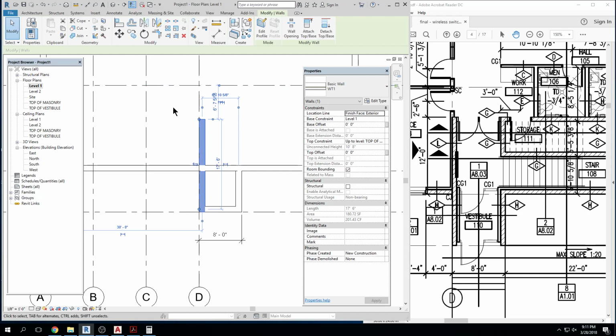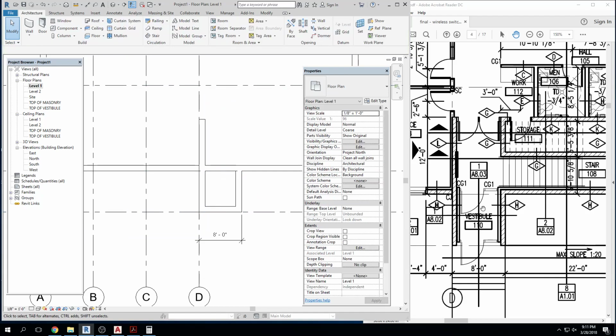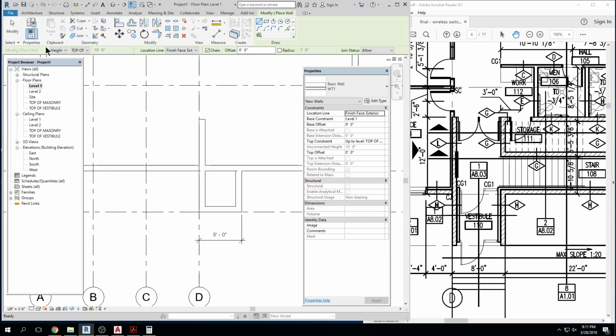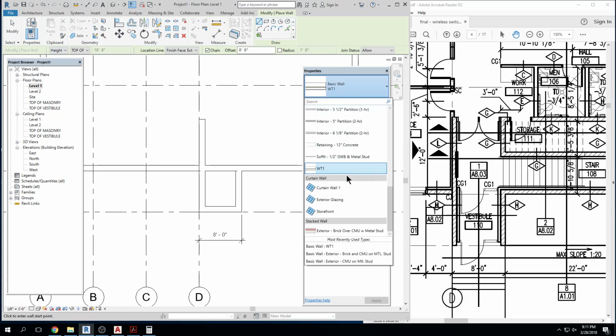And I want to remind you that when we create storefront, the storefront embeds itself into a wall, right? And so when I create the storefront, it's going to create an opening here, and it will make it look as if I don't have a piece of wall there, like the block wall there, right? So I'm going to go to wall now. Architectural, I'm going to go all the way down to my storefront.